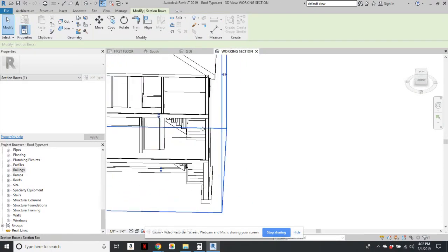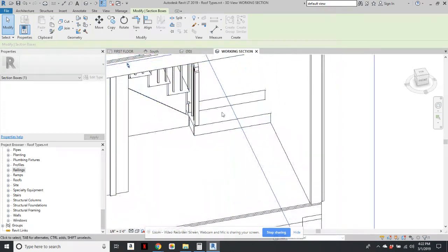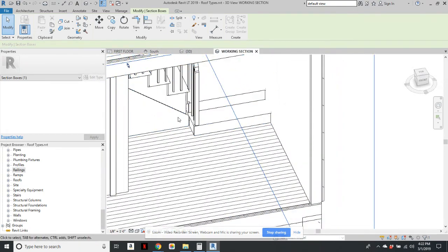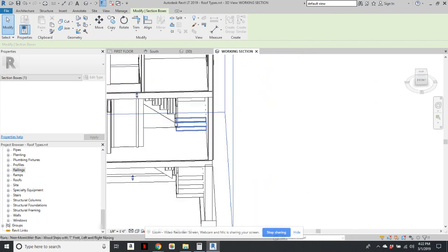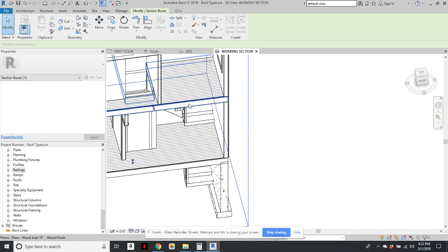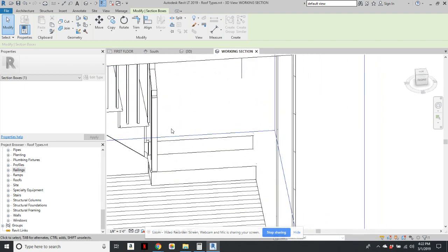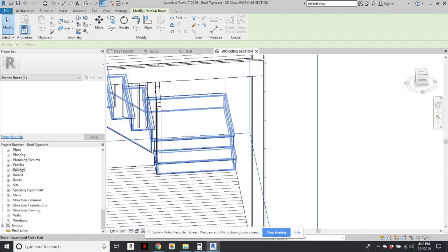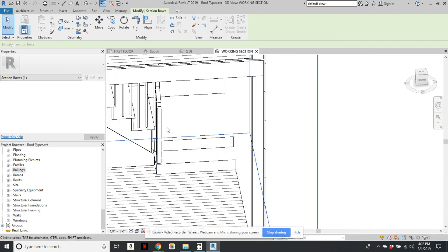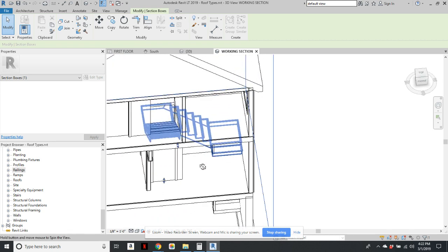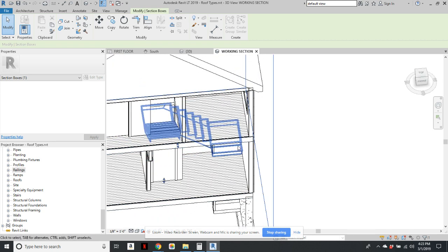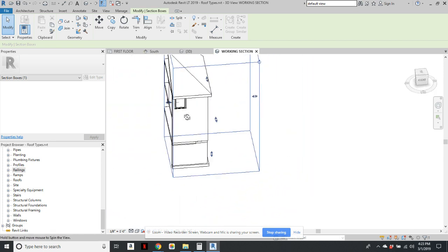So what I wanted to show you is sometimes on some stairs, there might be a decorative finish on the stair. And mine, for instance, I have a round here. And I wanted to show you how to do that. And I also wanted to show you how to create winders. My stairs at my house don't meet code anymore for current code requirements, but there's a winder, meaning there's a diagonal step up right here that's going across the landing. And what that does is shorten the length of the stairs as they have to be. And there's actually another winder up here on the second landing. So I'm going to show you how to do that today.